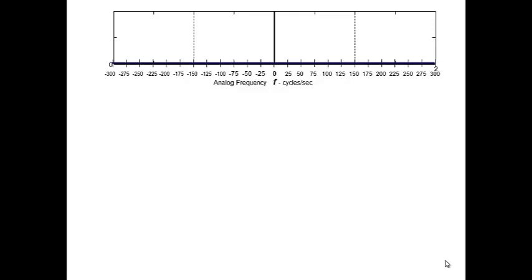And so, first off, I want to make one simplification, because I know I'm going to start drawing spectra. When I draw spectra, cosines are a much easier thing to draw spectra of than sines, because the Euler identity for a cosine is simpler than the sine one. So let's make the trigonometric substitution, the equivalent cosine version of this. Let's break out the frequency. What is the actual hertz frequency of the signal? 100 hertz, right? 100 t minus pi over 3.